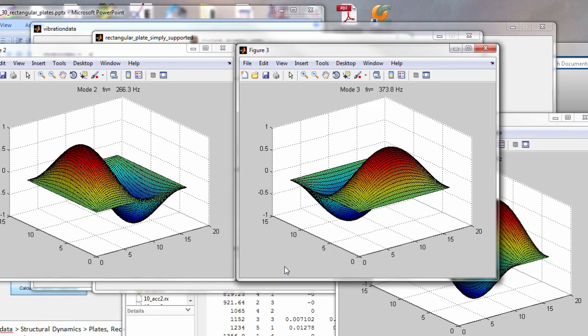In other words, the participation factor of each of those 2 modes is 0. If we had some reason to excite those and we were applying a base excitation or enforced motion, we would have to have a differing phase angle, or a differing amplitude, or both along the perimeter. But for a uniform constant amplitude in-phase base input along the perimeter, neither of those 2 modes can be excited.